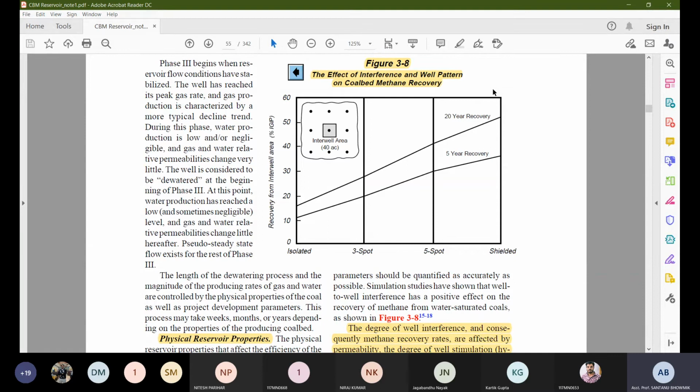Because coal is a very fractured rock, and again, the moment you are going to drill a borehole, you are going to induce fracture. Some of the rocks are totally fractured, it will fail, and up to a certain zone from the boundary of the borehole into the rock, there will be certain fractures. So it is not an intact rock case. There will be a rock mass case.